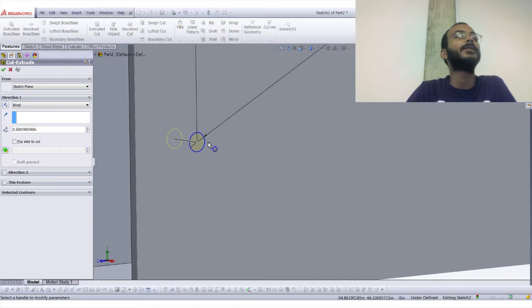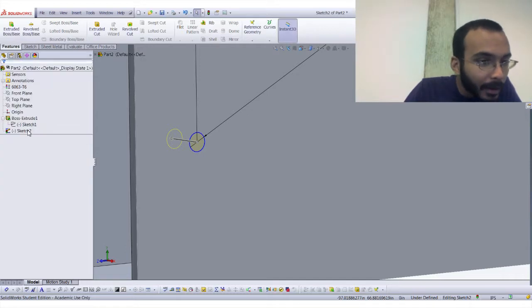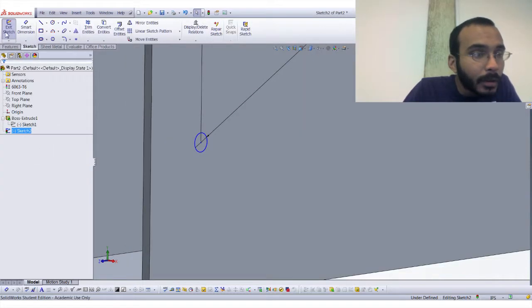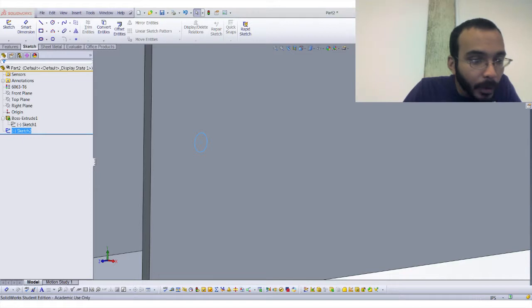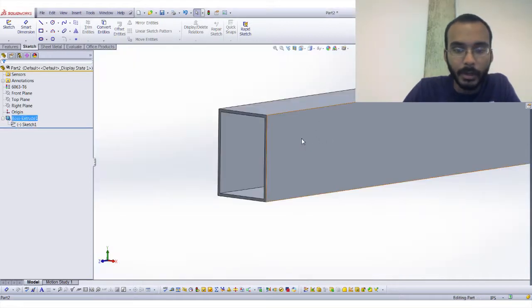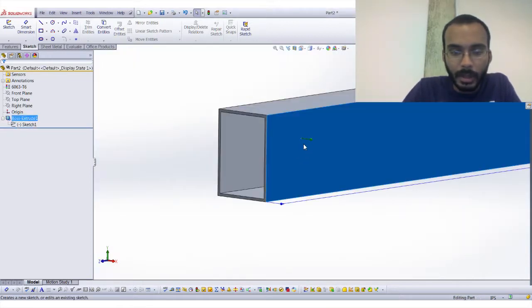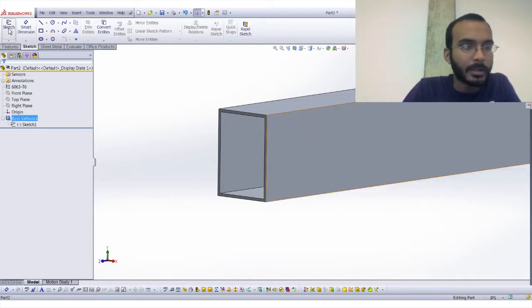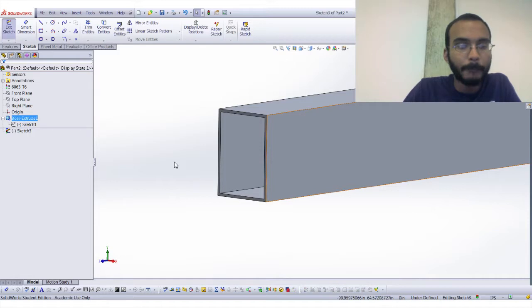Where are we at? We have a question? Question? How do you do that? Oh, I'll go back. Okay, so let me get out of here. If you're on the side of a part somewhere, you can either right-click and hit Sketch with a little sketch button right there, or you can click on it and hit the sketch button up in the top too. What sketch button? Do you mean the 3D sketch on plane?